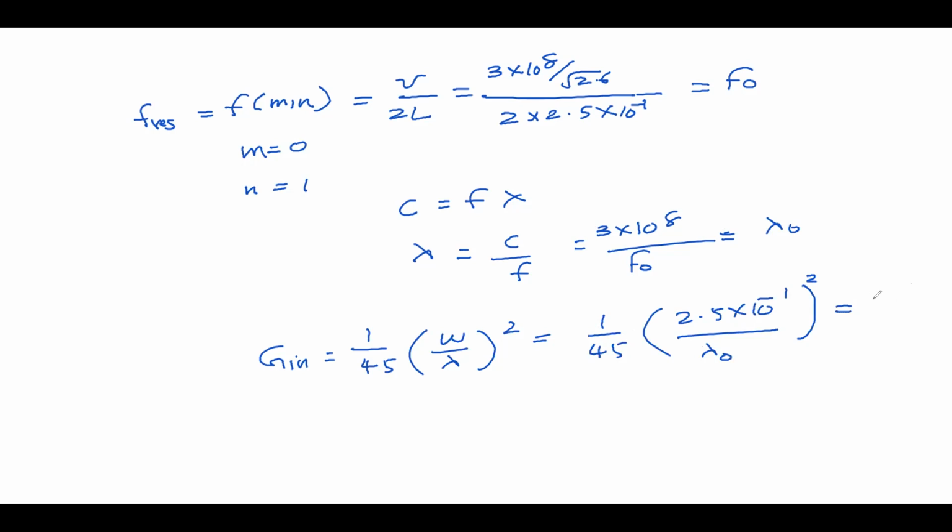Then you will find a certain value, but it will be 1 over the impedance of the antenna, right? So you will get 1 over R_in. From this equation, you need to find the R_in by taking 1 over the G_in value. And then once you find the R_in value, you can find the inset feed length that is required to match the feed line to the antenna.